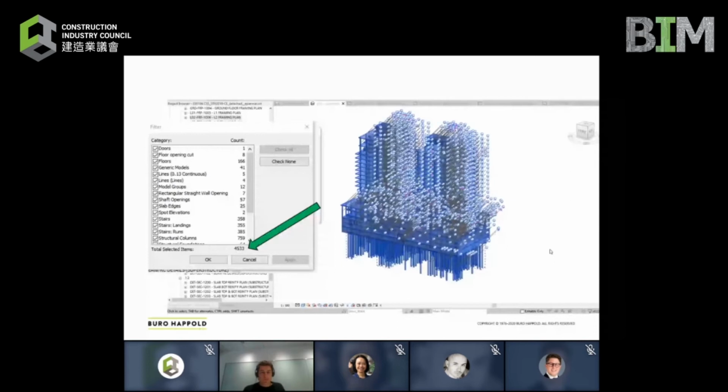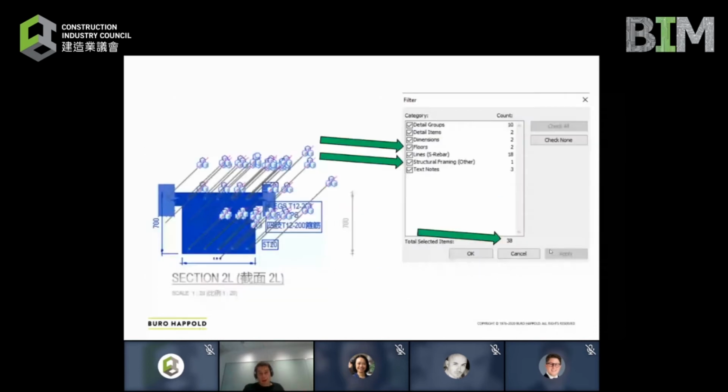So what's the problem? Again, if we look even on a drawing, that exact same structure exists. So when you look at this, and this is the kind of thing that someone with an engineering background does, they combine everything we just talked about into one thing. First of all, we talked about efficiency in drawing production. So you say, because I have the three-dimensional model, I get this section for free. But actually, when we look at what's on the 2D drawing as just data, we ask the computer, what is the data that I'm reading as a drawing? We can see here that there are 38 digital objects that have to be created in order for me to see that picture and interpret it.